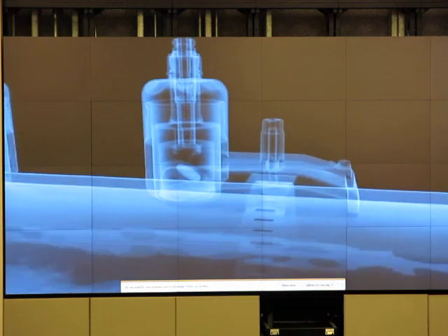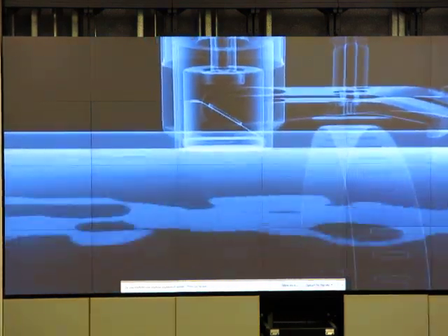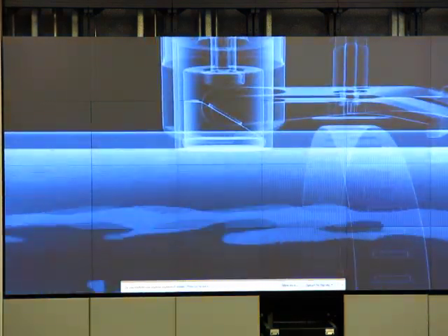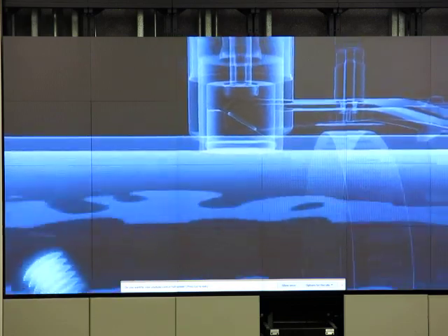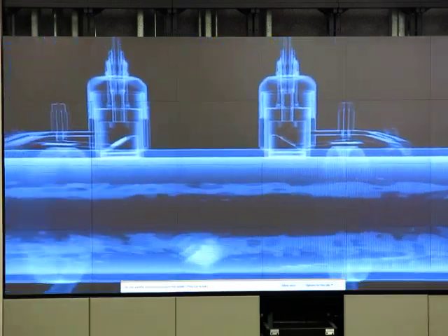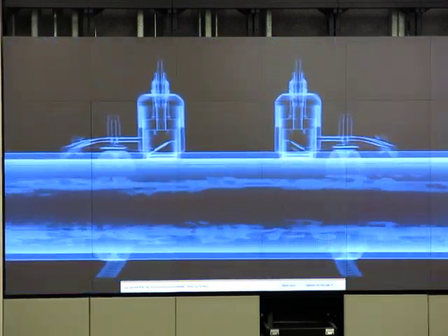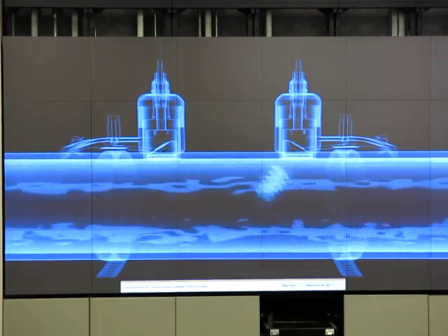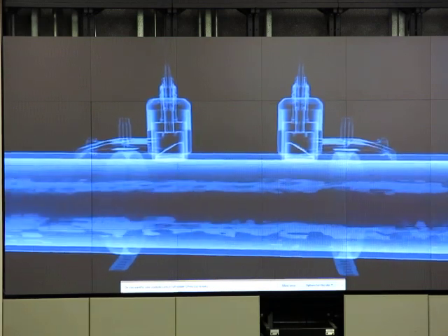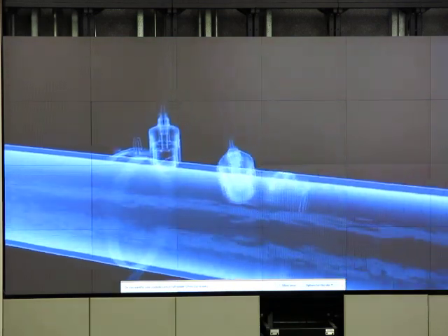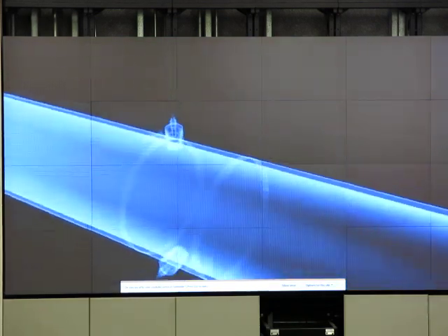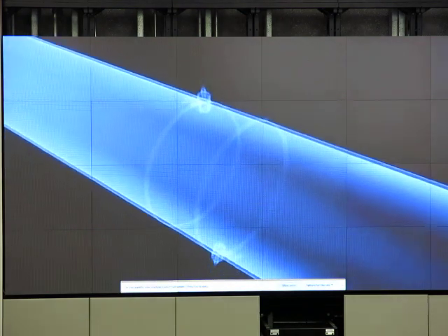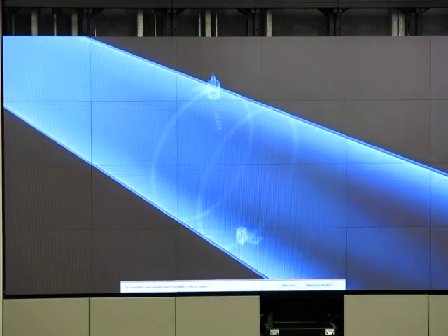With clamp-on sensors, the ultrasonic signal is passed directly through the pipe wall and into the fluid. The signal continues through the fluid, is reflected on the opposite pipe wall, and then measured by the second sensor. In this example, with a two-traverse installation, the clamp-on design is unique because flow rates can be measured in very large pipes, up to 4 meters in diameter.